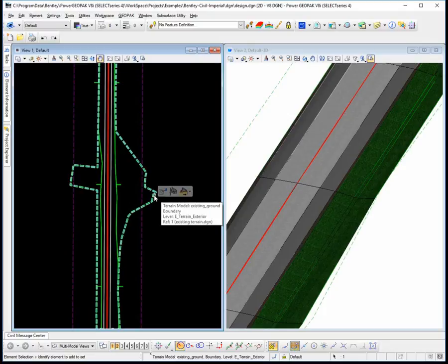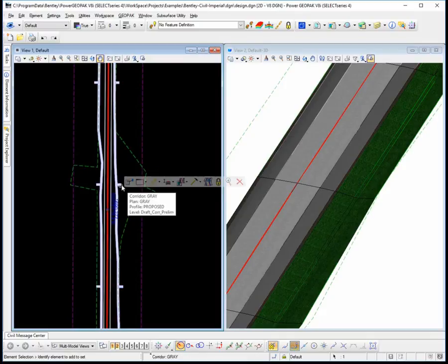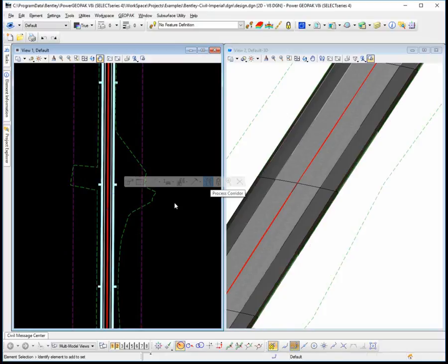And so if I select my active surface and I clear the activation of the terrain model so I don't have an active surface, then as I reprocess my corridor, I'm going to take out the processing times required for the end conditions, and it's going to process quite a bit faster. And then once I start working on my slopes, then I can reactivate my active surface.